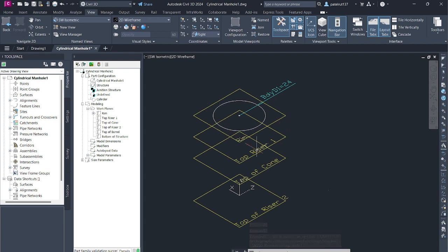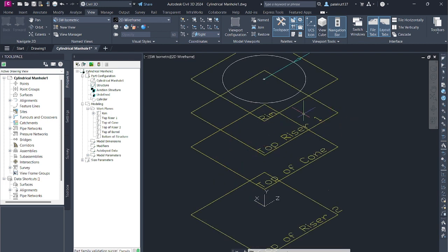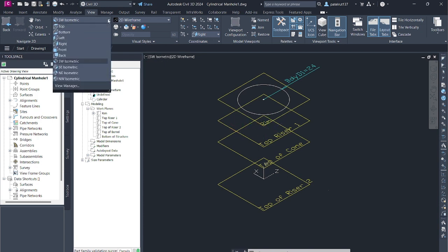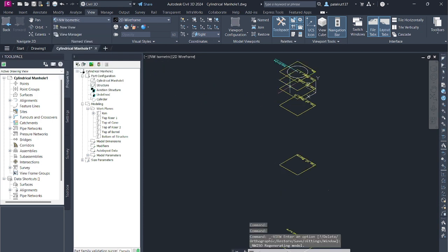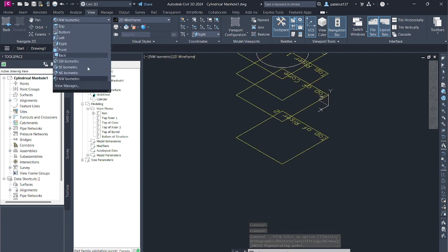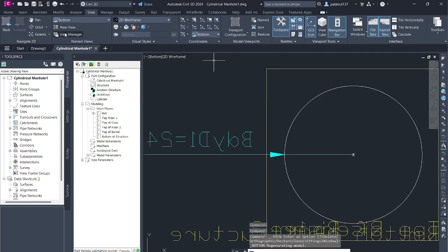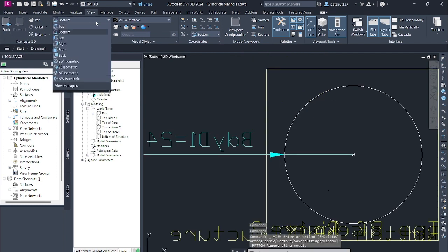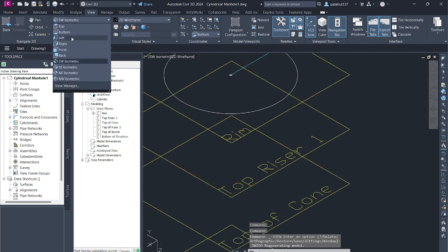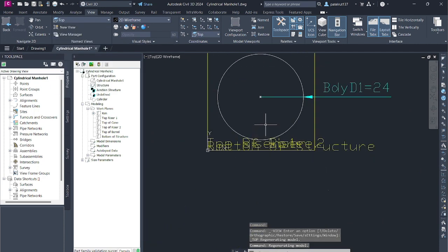Do a quick visual check on the Part Size Creator dialog box to verify that all values are non-zero. If any of the properties are displayed in the Part Size Creator dialog box as 0, the part will not insert into the drawing properly. Now add a few pipes to your test parts list. Exit the Parts List dialog box. A new parts list is created. Create a pipe network by layout that contains approximately 3 structures and 2 pipes. Observe how your structures are displayed in Plan, 2D Views and in 3D View, Object Viewer.